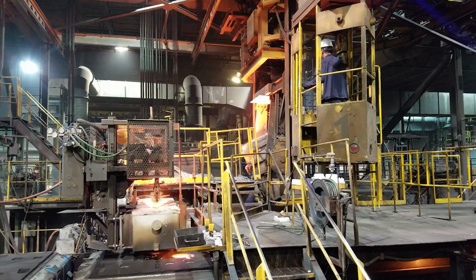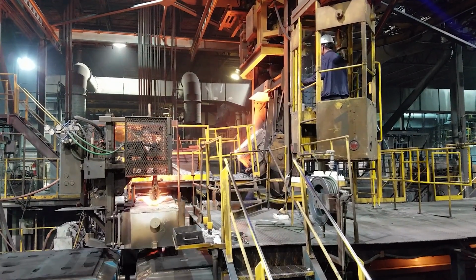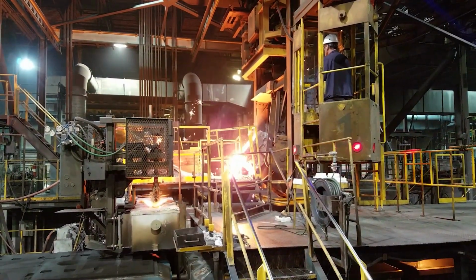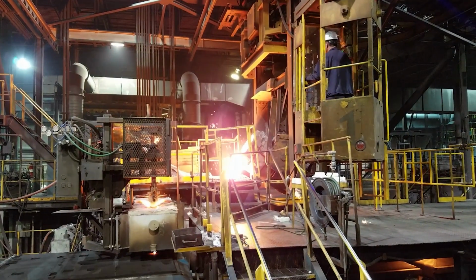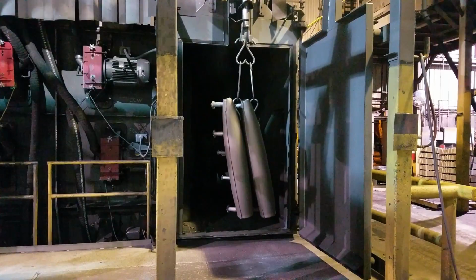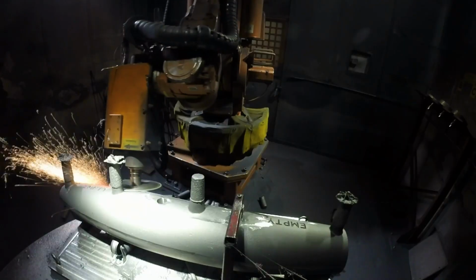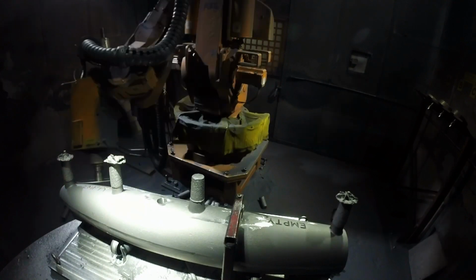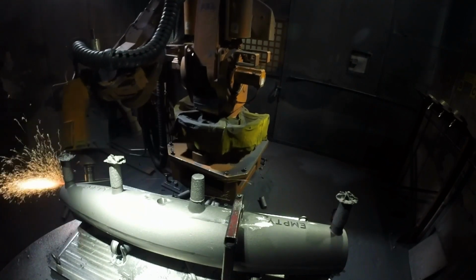Now the liquid iron goes to the molding line. We pour the liquid iron inside of the mold. About 3 hours later, that casting is solid, cold enough so that we can punch out and wait a little bit more before we shot blast, and then we grind. And then we can inspect and ship. So basically we can make a casting one day and ship on the next day.